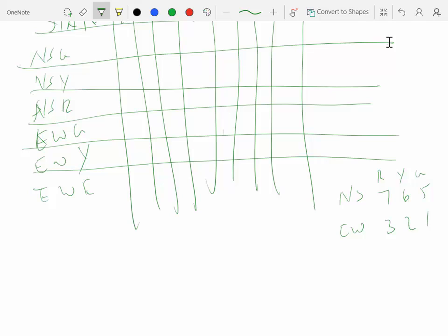And also remember that 1 equals off, 0 equals on, right there. And what we want to do is create this table, and we don't have to create these tables. We could assign our pins one by one. That'd be a pain in the neck and generate some very long code, because you'd have to have 6 lines for every time you want to turn on and turn off your LEDs. It'd be easier to just do it with 1 right there.